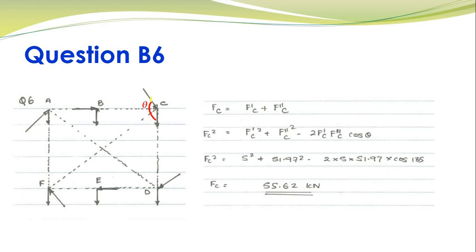Now looking at the resultant force acting on bolt C. Again, resultant force Fc is basically the vector sum of primary shear plus secondary shear. So again, this is my cosine rule. This time around I have to be careful regarding my angle theta here. Quite easy, this is 90 degrees, so done. You can see that this angle is also 90 degrees over here.